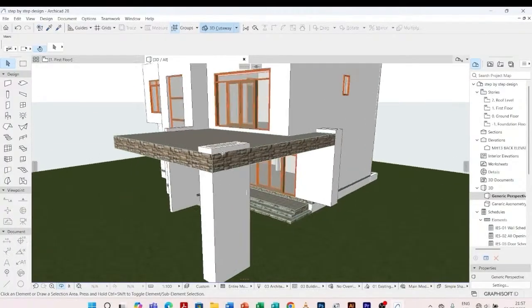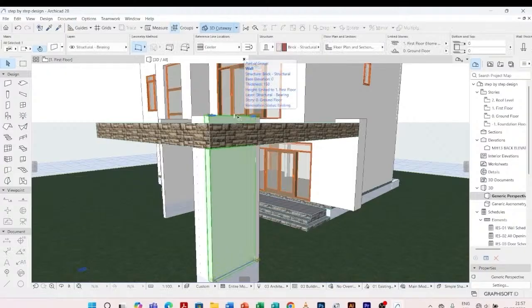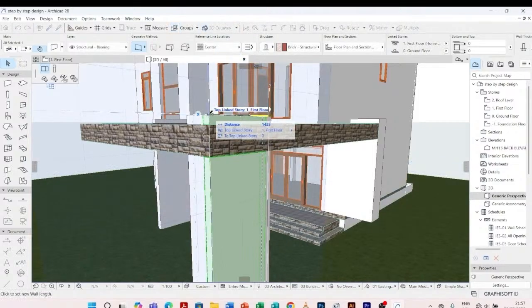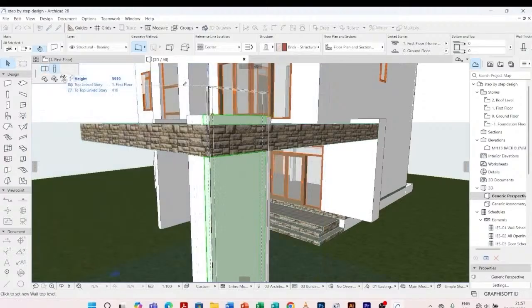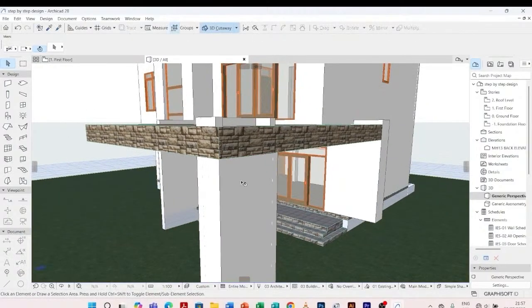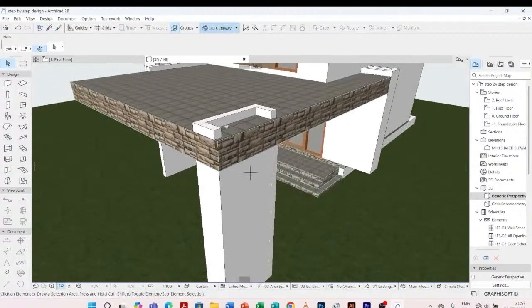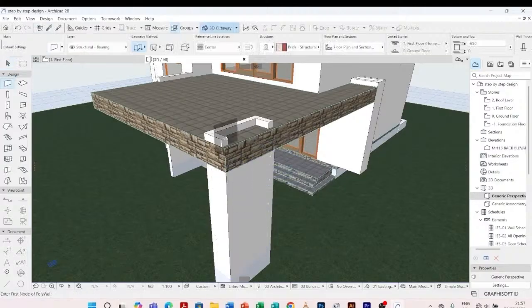I'm going to extend these walls down. So I click on one wall, I get any point. For this case, I can go with this point, and I'm going to stretch the height. So I click on this, I move it down. I hold on to shift so that it is in line up to there. Now I can copy parameters and inject it in these other walls. So I copy parameters of this wall, then I inject it in this.